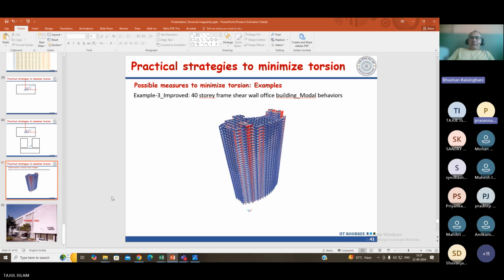You restrain the top of the column, remove the restraint and apply the force in the diagonal direction. So you can apply the lateral force at 0 degrees, 90 degrees, and also at 45 degrees. Then you can check what change is coming in the shear forces, and whether the design is satisfying for that column or not. So you can check manual versus software on that model. Once you calculate your torsional stiffness, you can check it manually.